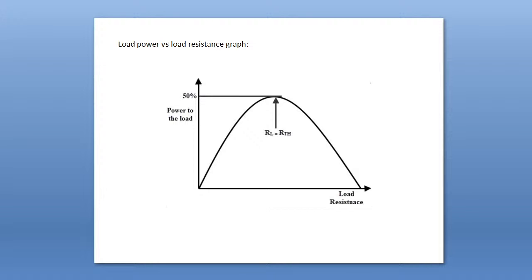We cannot select load resistance equal to the source internal resistance of the circuit, that is the Thevenin resistance, in real applications, because the circuit will get damaged due to the heating effect, since maximum power will transfer from source to load. As a result, maximum heat will be produced in your circuit. Therefore, we never select load resistance equal to source resistance in real applications of any circuit.